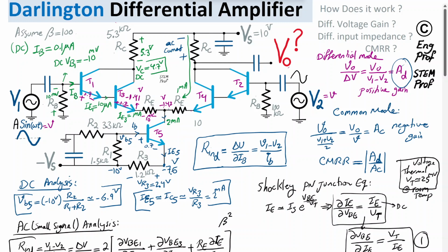And that's going to be large, because this transistor T5 is boosted: there is a resistor and AC ground. See, this cap is the bypass cap. That AC VEE is short and would ground this node to AC ground, virtual ground. So there is an R3 in the emitter of transistor T5, a sort of degeneration, and that results in boosted output resistance for T5, which is going to be on the order of mega ohms, a couple of mega ohms actually.